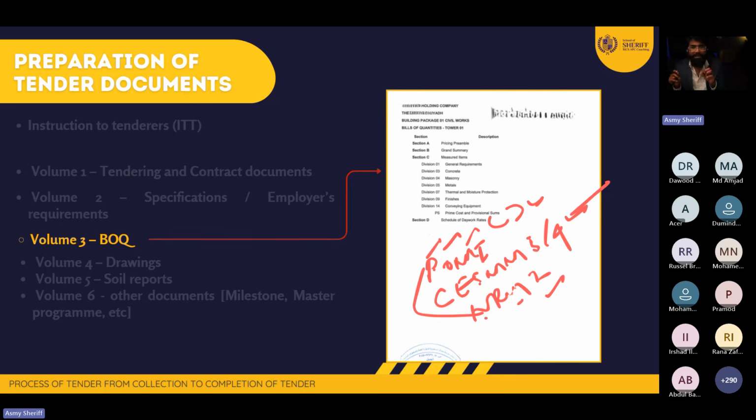If you're going to measure A, B, C, X, Y, Z, all the measurable items in a building, they provide a list and tell you in what unit you need to measure. You only need to take the drawing. They're telling you that all the concrete should be measured, and any holes less than 1 square meter we need to avoid. So I'm going to put my cursor, measure the concrete area, all the bits and pieces, and put them all together. And I identify 2 places with holes less than 1 square meter, so I'm going to deduct those. This is the total concrete area. Finish. Similarly, there are many items based on each and every element that you're doing.